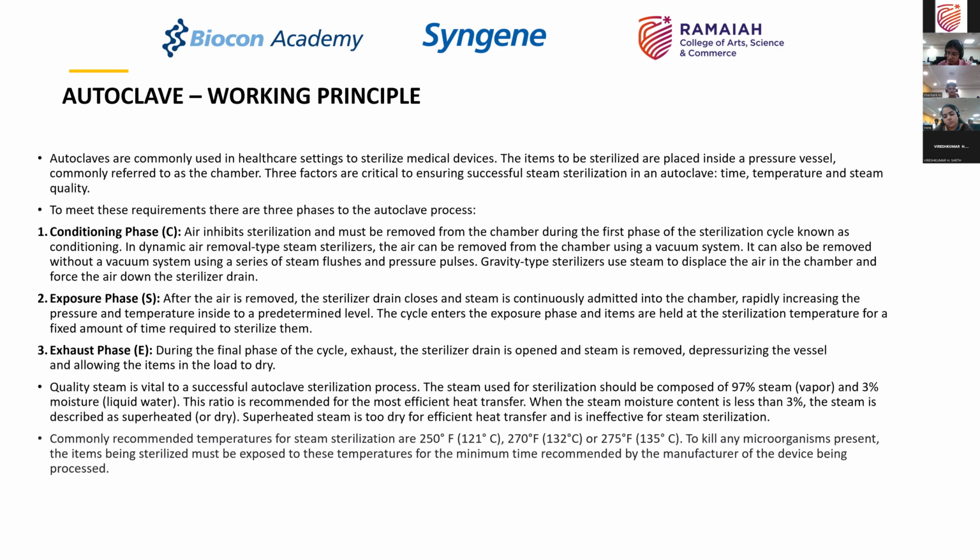You cannot open a pressure cooker or autoclave when it is in a hot condition, because the steam can burn people who are around that autoclave. So it is very important to have the conditioning phase and exposure phase to achieve the right sterilization, and the exhaust phase to cool down the contents and to dry the load so that you can remove them and start using them. In the industry, you are going to use mechanical means to run the exhaust phase.